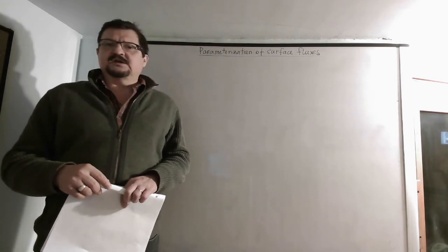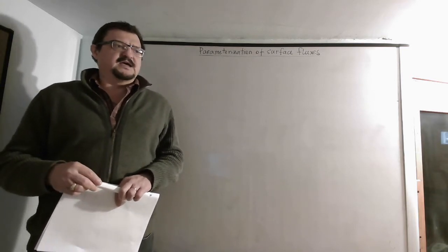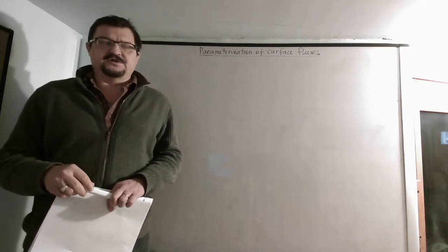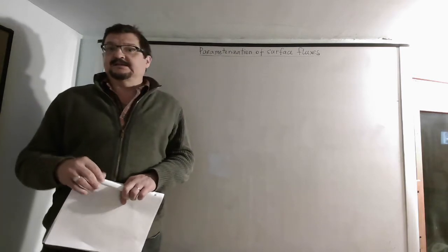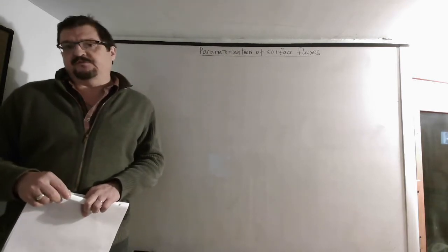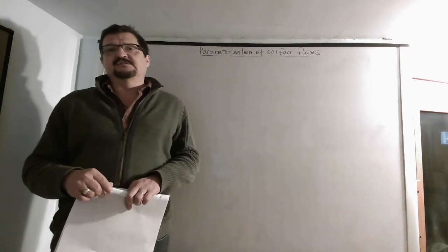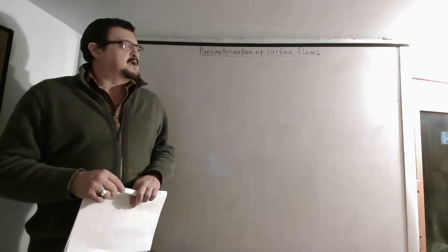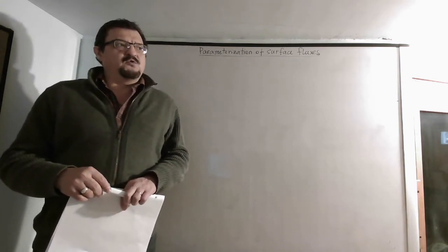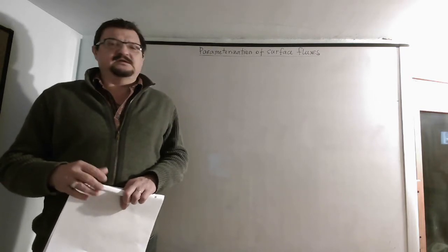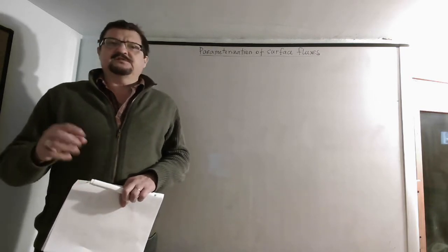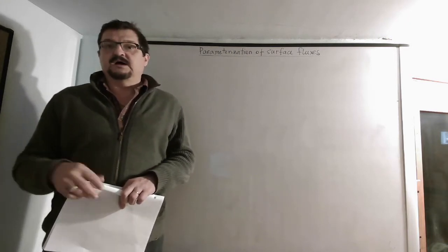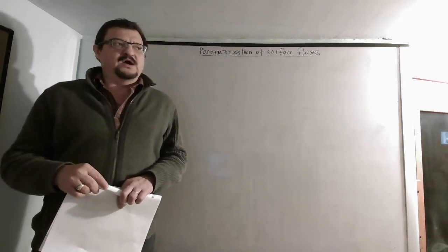And in certain conditions that we actually considered, like if our grid scale is within the so-called inertial subrange of turbulence, then we could analytically derive very useful expressions for fluxes, for eddy diffusivities, and other concepts using Kolmogorov theory of turbulence. Now, all this that we've talked about in the last lecture concerns fluxes that are well within the fluid, away from surfaces. Why is it important?